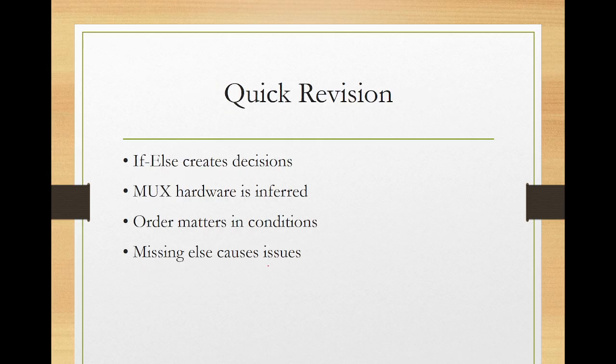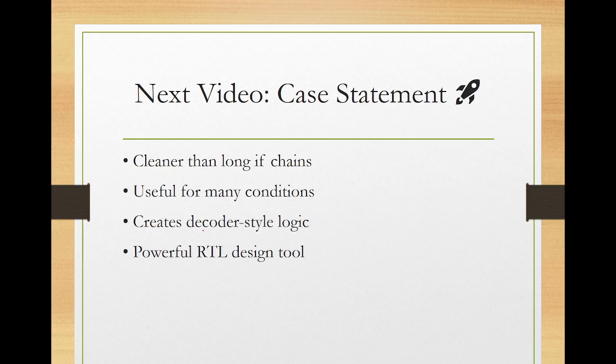So let's recap. Today we have learned if-else creates hardware decisions. If-else often becomes muxes. Hardware does not execute software. Priority matters. Missing else can create issues. Missing else can create latches. Verilog describes hardware, not instructions. Today, we discovered one if statement, one decision, one multiplexer, real hardware.